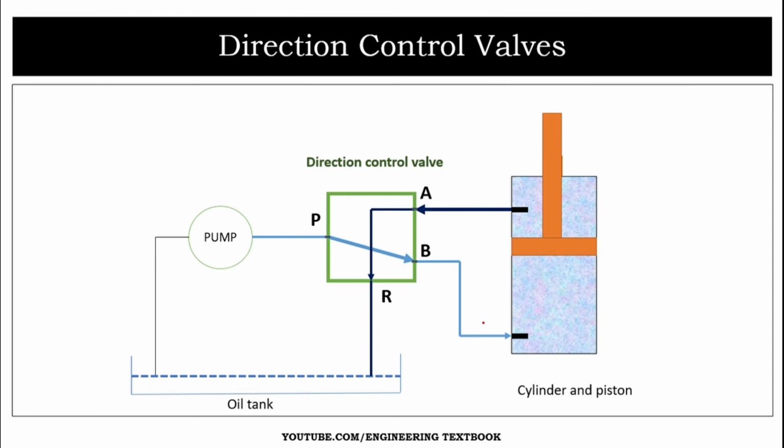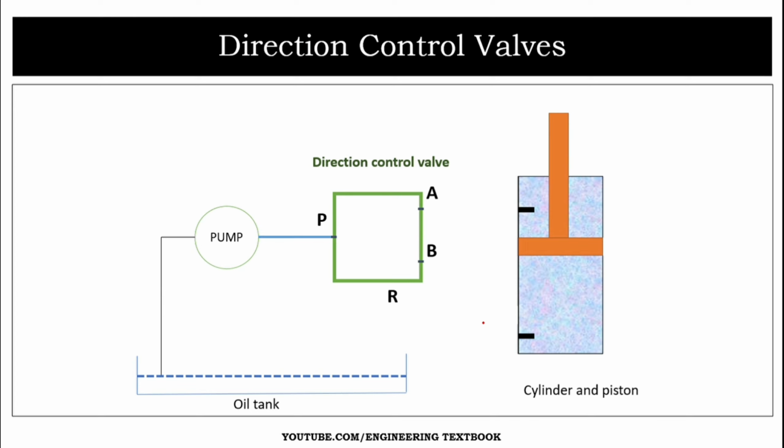Now let's see case 2. In the next stroke, port P will be connected to port A and the oil moves the piston in the downward direction.